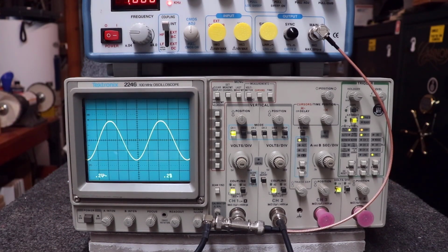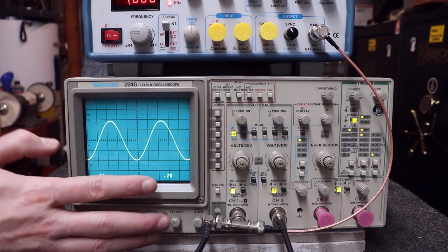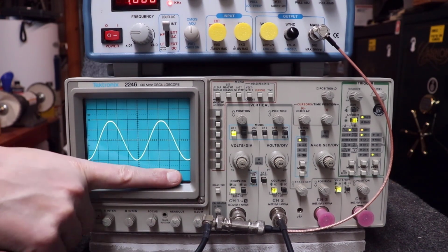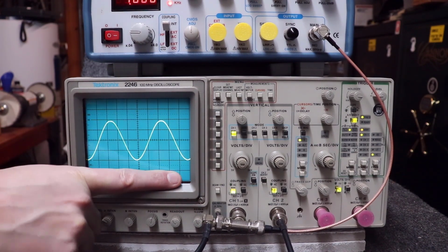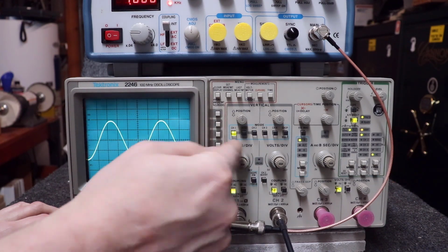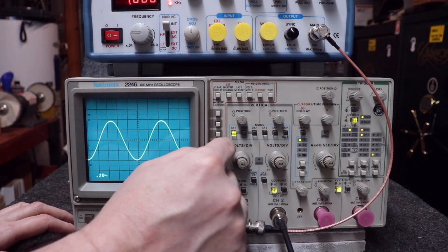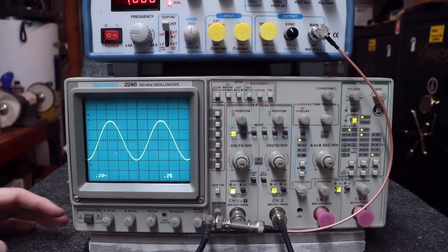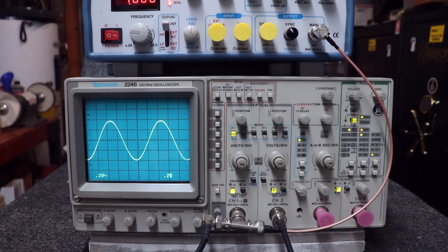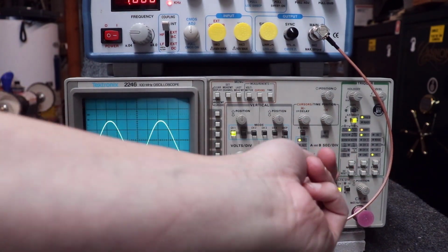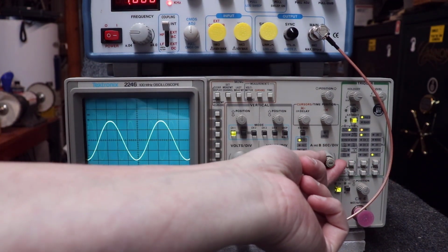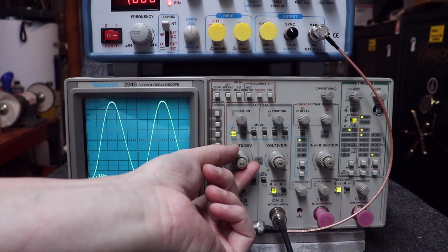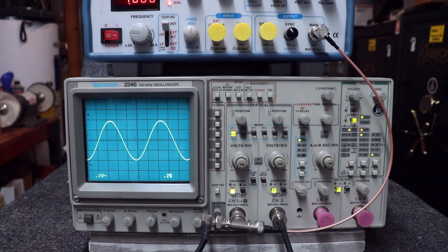Now, I can do that math myself. On an older oscilloscope that doesn't have these little displays down here to tell me, you actually have to come over here and read it on the dial itself. So you just read on the dial and it would say 0.2 volts per division, right? But this one just happens to display it on the screen. Same here with the milliseconds. It shows the time base. So if I change the time base, I'm changing that. If I change the volts per division, I'm changing the readout on it.